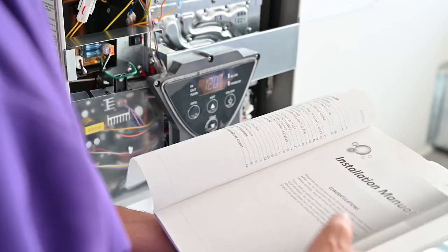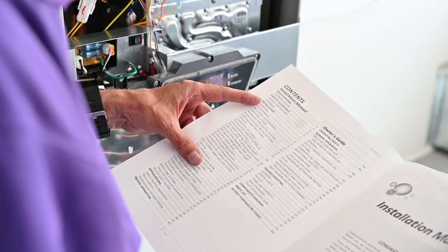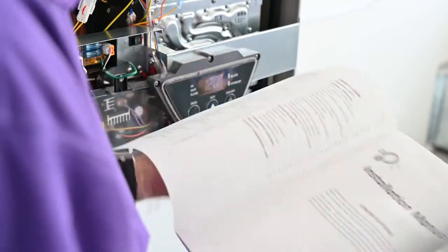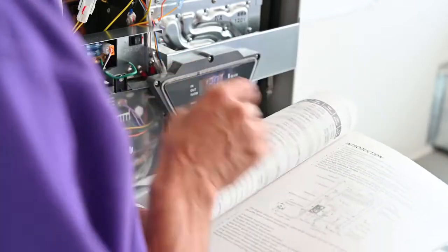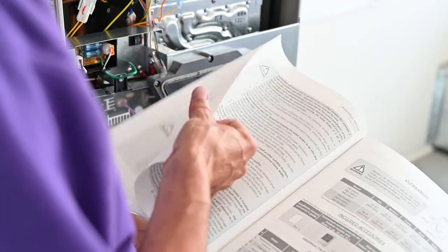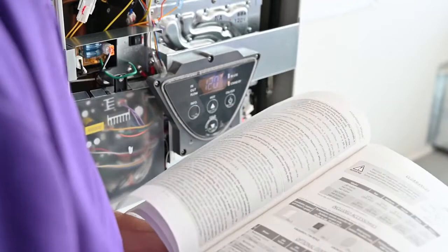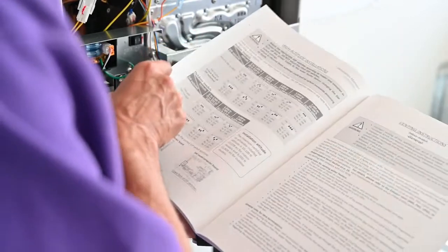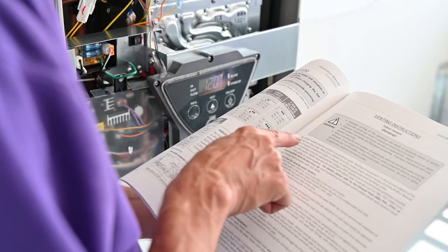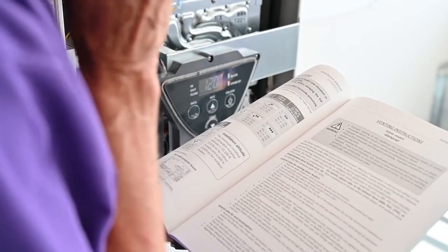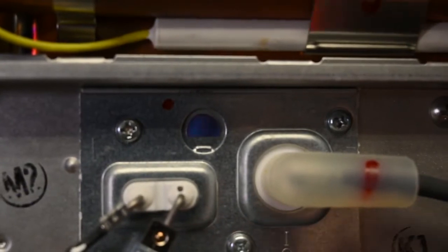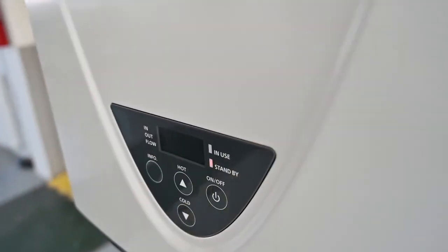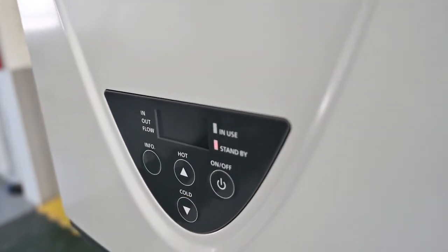Installing a tankless water heater. Before installing a tankless water heater, it is important to always consult the installation manual that is provided with the unit. This manual will provide full details and specific guidelines regarding required clearance, venting limitations, and utility requirements such as gas, water, and electricity. Since this is a fuel-burning appliance, it is also very important to follow all national, provincial,